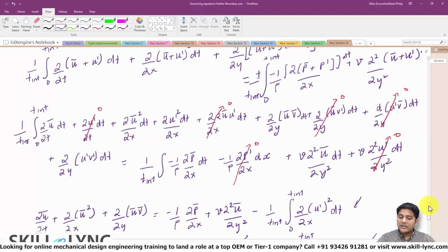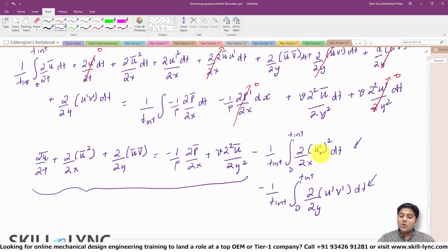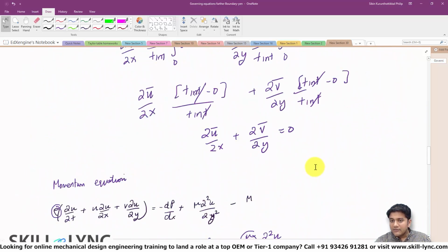Now these two terms don't necessarily cancel out to zero. So for example, when you are integrating the instantaneous fluctuations as a function of time, we proved that that is going to be zero, right? So the idea is, if you're looking at a long enough time, the fluctuations have both positive and negative values, and they are equal in number, and that is why when you average them, it becomes zero, right? So you can think of that as a curve like this.